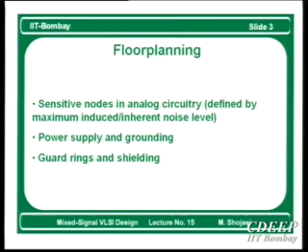Of course, this question may come to your mind: okay, but the effective resistance of these lines is very small. Therefore, effectively, any switching will not create any noise, or we can call it bouncing, on the signal. But then we will see what the reasons are for these types of bouncing. Therefore, we have to be careful about power supply and grounding when we make a floor plan, and also afterwards when we route.